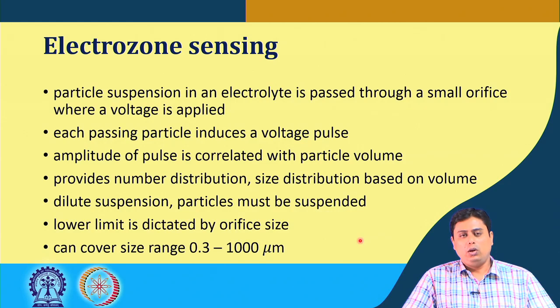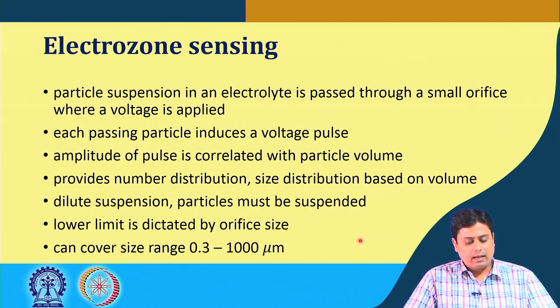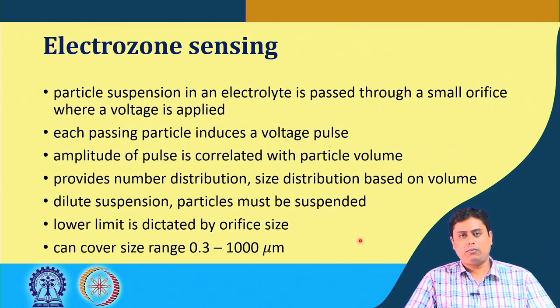Now, the lower limit of the linear dimension that you can achieve by this methodology is dictated by the orifice size, that is, how small your orifice is, basically that will be the lowest size particle that you can determine. Typically, it can cover the size range from 0.3 to 1000 micron size particle.